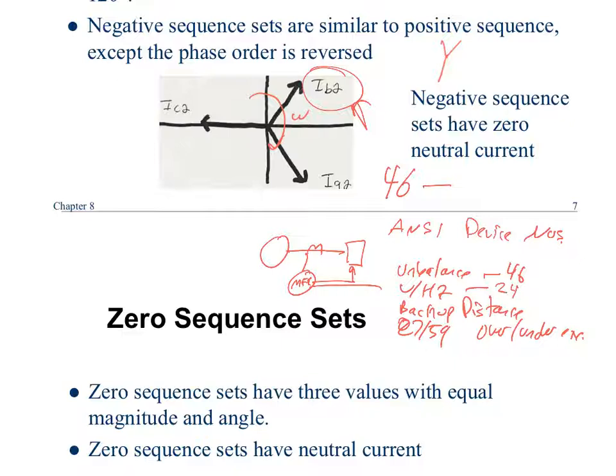So remember what I talked about when you have polarizing quantities or operating quantities in relays? You can actually specify positive, negative, and 0 sequence to trip. Because instead of looking at the actual phase quantities, which could be really high, you can look at negative or 0 sequence, which are calculated from those phase quantities, right? The relays themselves are just looking at phase current A, phase current B, and phase current C. And then it runs through some calculation to give me positive, negative, and 0 sequence.